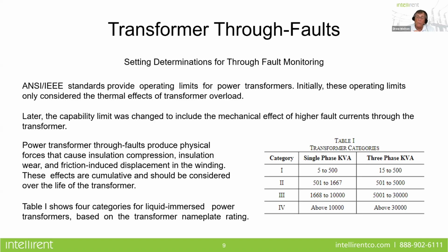So if you were going to switch out a protective relay system that has captured historical data on through faults, you want to apply that precondition to any new transformer protective relay that you're going to put on the system so you don't lose that information.